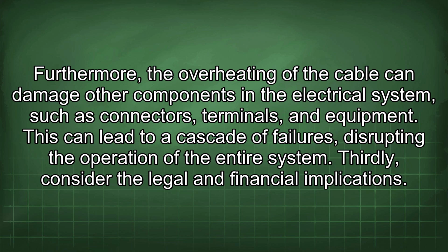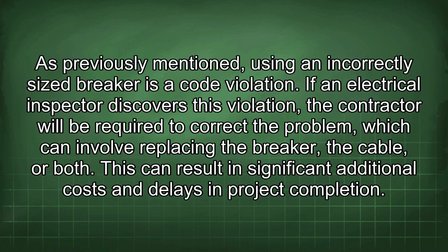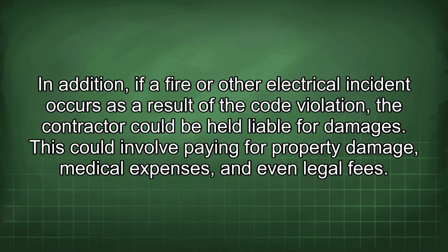Thirdly, consider the legal and financial implications. As previously mentioned, using an incorrectly sized breaker is a code violation. If an electrical inspector discovers this violation, the contractor will be required to correct the problem, which can involve replacing the breaker, the cable, or both. This can result in significant additional costs and delays in project completion. In addition, if a fire or other electrical incident occurs as a result of the code violation, the contractor could be held liable for damages.